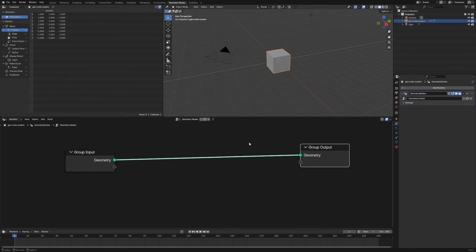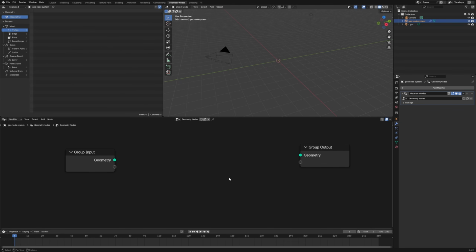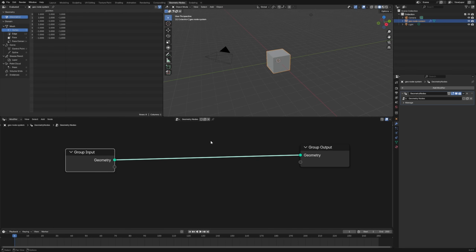There's been no change. If I hold Control and then right click, at the bottom of the screen you're going to have dynamic options as you look over things. Hold Control, now it says select, 2D view, cut links. So I want to cut the link, and now it's turned off because this connector has been turned off. I hold Control and draw. I can also hold Alt and then right click, and it'll do a dynamic connector. That's done through Node Wrangler. It makes it a lot easier to work with all these different nodes.